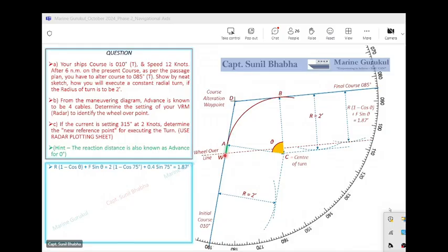That means right from point W, whiskey point, how much time is the ship going to take to reach point Bravo? You see this particular segment of the track, whiskey to Bravo. We will be giving a helm order. The vessel will be moving on a curved path. And during this curved path, it is not possible to counteract the current using the chart work techniques.